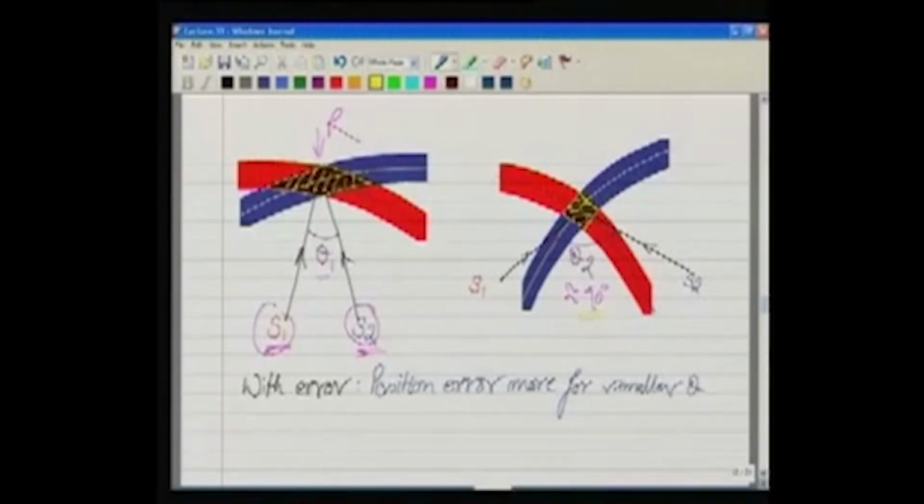So this is why we say the angles should be nearly equal to 90 degrees. A good GDOP, or a good geometry, could be one where one satellite is on top and 4 satellites are on the horizon. So this is a good geometry. It will give very good geometric precision, or the dilution of precision because of the geometry will be less. While if all the 4 or 5 satellites are hanging up there, the dilution of precision because of the geometry will be large.